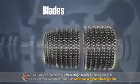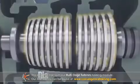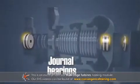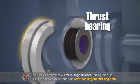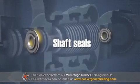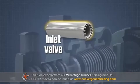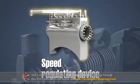The fixed and moving blades, which convert the kinetic energy to mechanical energy. Diaphragms that hold the fixed turbine blades. Journal bearings, which maintain the radial alignment of the rotor. A thrust bearing to maintain the axial alignment of the rotor. Shaft seals to contain the steam in the casing and keep any air out of the condensing unit. An inlet valve or valves to control the flow of steam to the turbine. And a speed regulating device.